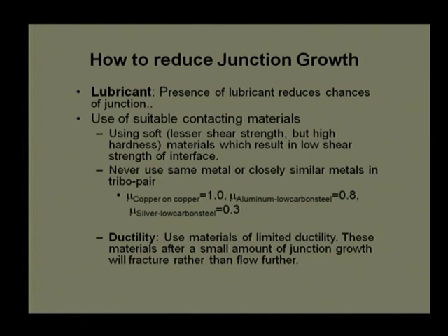Sometimes we play with the ductility also. We use a low ductile material which can be easily ruptured. Apply a slight force on that, and it can be easily ruptured at the interface, and that will provide a low coefficient of friction. However, there is a problem. If that rupture happens very rapidly, or it deteriorates the surface softness, then we should not use this kind of suggestion. We should use some sort of lubricant, or many times we use water to lubricate the surfaces.